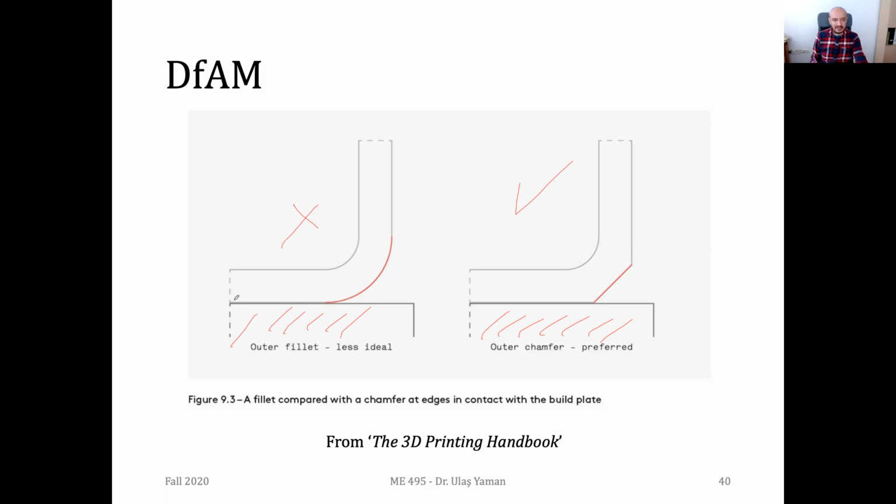Yeah, it's another possibility. But what about the slopes here, especially in this region? If you consider this part, we have very low angles, right? Shallow angles, and you may need to have support structure. But if you look at here, the angle is always the same. It's around 45. So without using support, you can have proper planes.